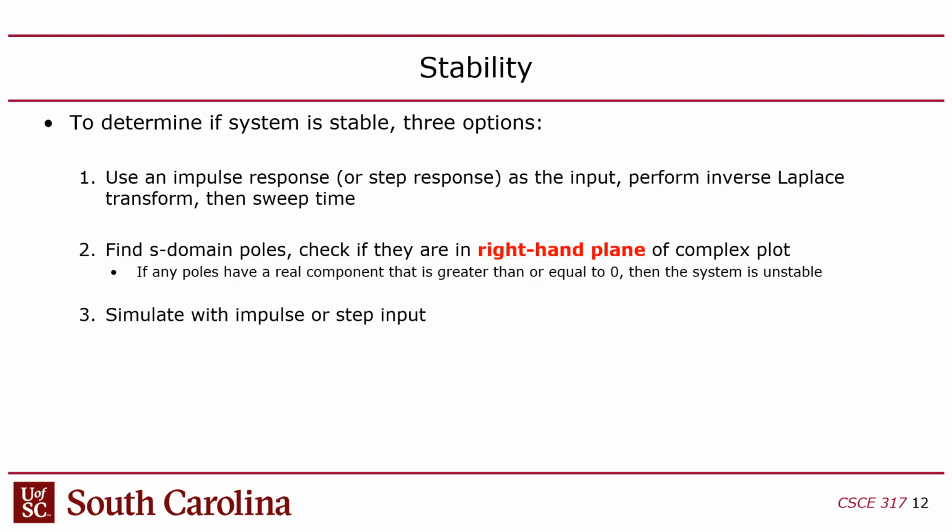That's an impulse, and the reason people use that is because there's two reasons. One, it has a very simple Laplace transform. The Laplace transform of an impulse is 1 in the S domain. But the other reason is that an impulse contains an infinite number of frequencies. It's basically saying, I'm going to hit you, because in order to add up sinusoids to create an impulse, you have to add up an infinite number of sinusoids, as you would also for a step function, where you go from 0 to 1. So if there are any frequencies in there that cause a blow up, instability, you'll see it.